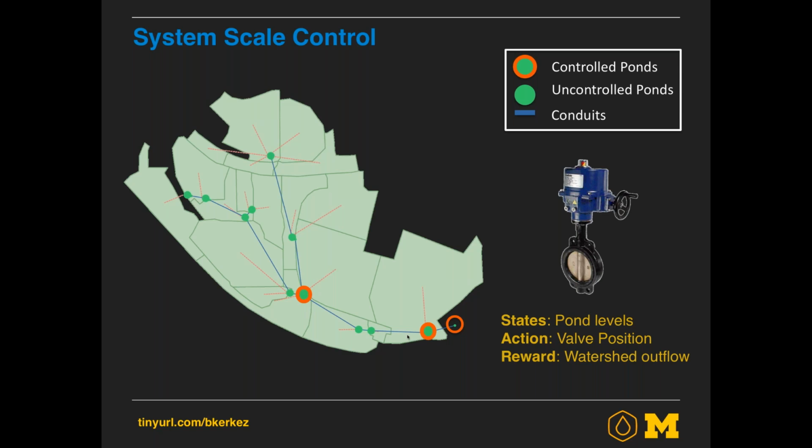And that's a really overwhelming problem, because if you think about a system that even has just 10 valves, and let's say you can only open those valves 10% at a time. So maybe it's closed, 10% open, 20% open, 30% open. Think about the number of permutations you'd have to run through in real time to figure out the best control strategy. During any given time step, you have 10 to the 10 possible combinations. That's 10 billion combinations that you could run, and you've got to figure out which one is correct. So obviously that's not that easy.